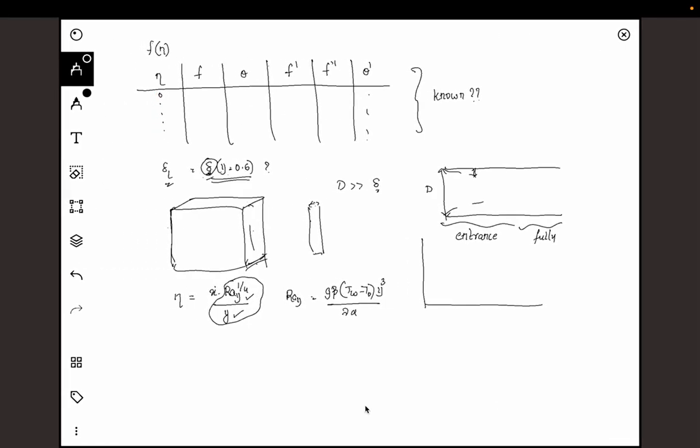When you observe these values, f prime will be proportional to v. So v is minus alpha times Ra to the power half times f prime. It goes something like this. What we are trying to do is find the particular value of eta where this will be close to 0. When I've done it, this is a little less than 10, but if you take it to be 10, then this eta will be 10, and the value of x at that particular eta is my boundary layer thickness, delta times this entire quantity you have calculated now. So this will give you an estimate of what the value of delta can be.